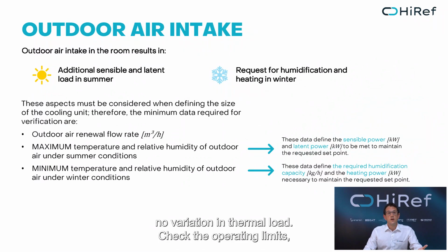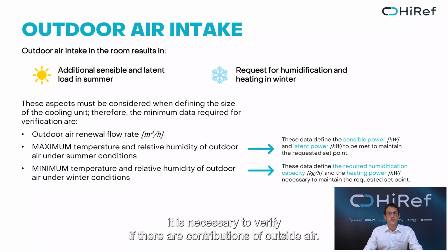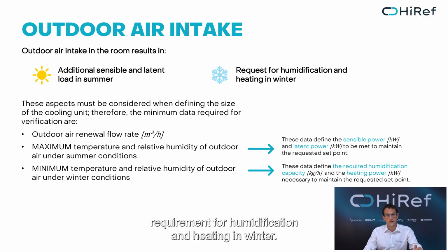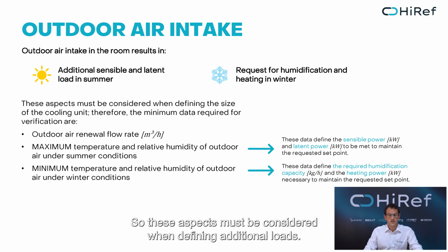Check the operating limits. It is necessary to verify if there are contributions of outside air. This implies sensible load and additional latent load in summer, and a requirement for humidification and heating in winter. So these aspects must be considered when defining additional loads.